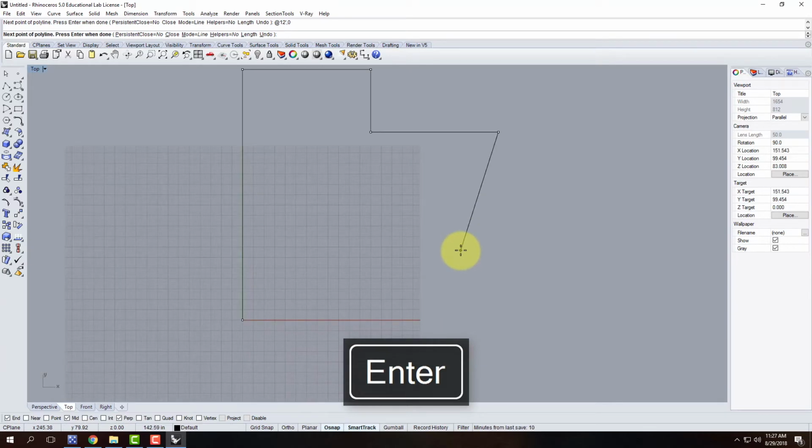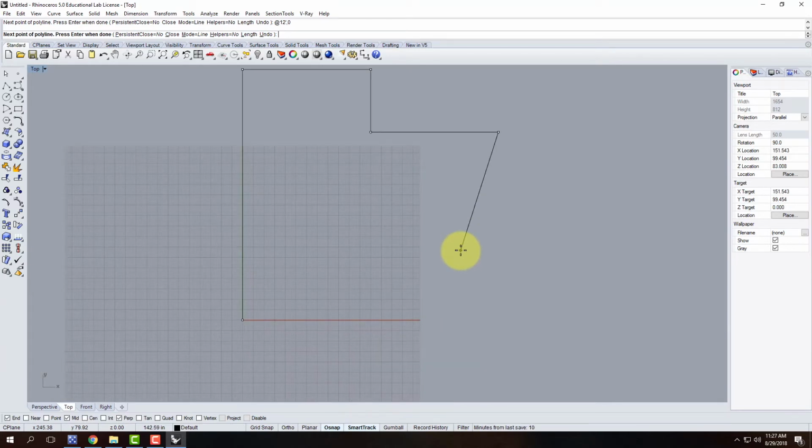You'll notice on the handout, it does spell out all these coordinates that I'm telling you, because I'm following along. So if I wanted to go down 12 feet, this would be another relative coordinate, @ 0, comma, negative 12 feet, because I'm not going anywhere in the x direction and I'm going down 12 feet in the y direction.